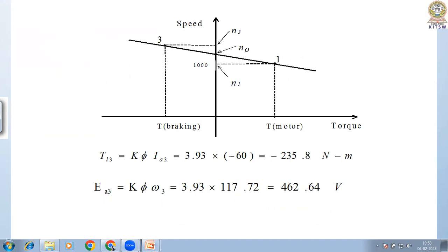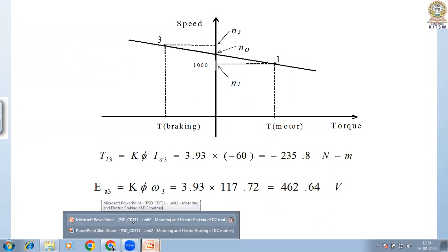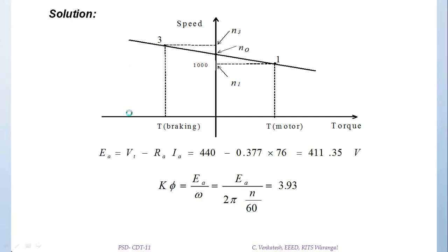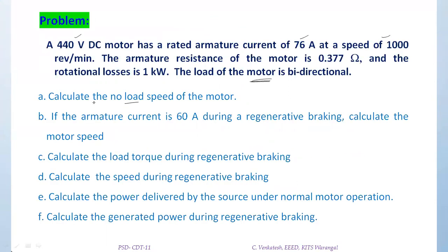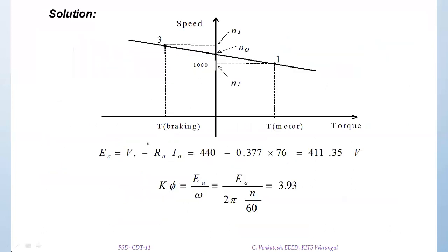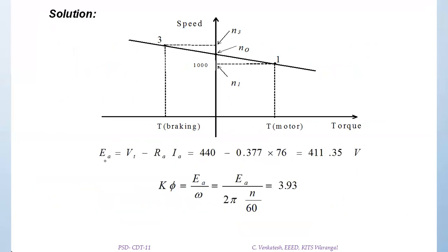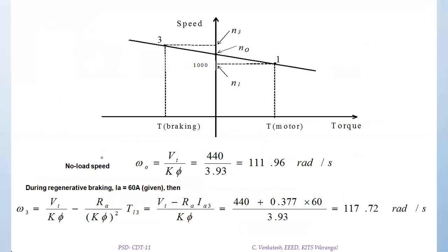So we shall take one by one. Calculate the no load speed of the motor. To calculate the no load speed, you need the back EMF relation. So therefore, first you are finding the back EMF.